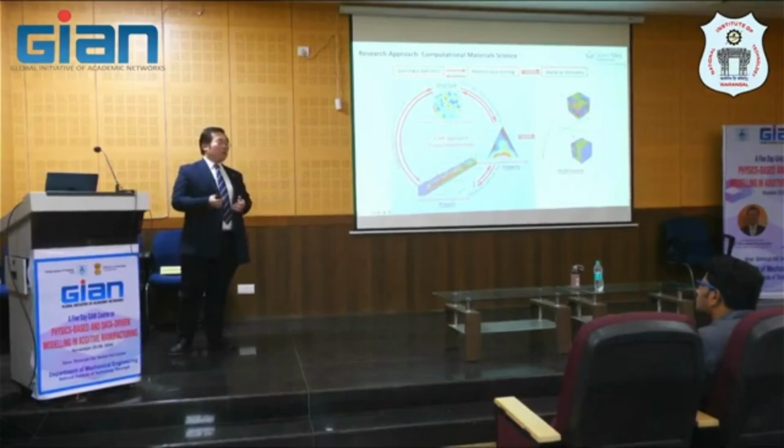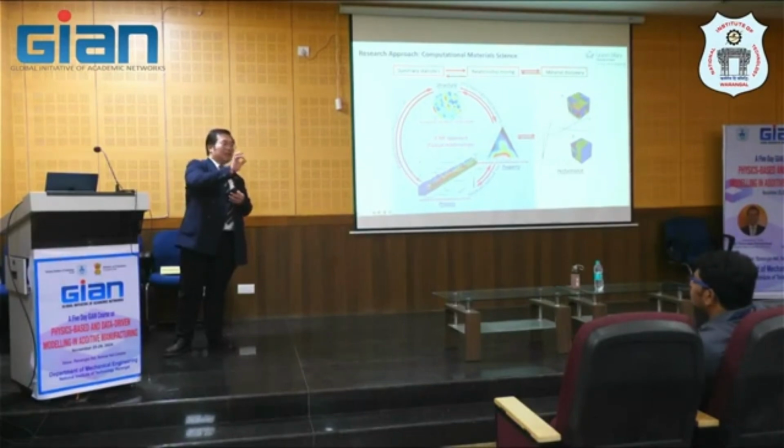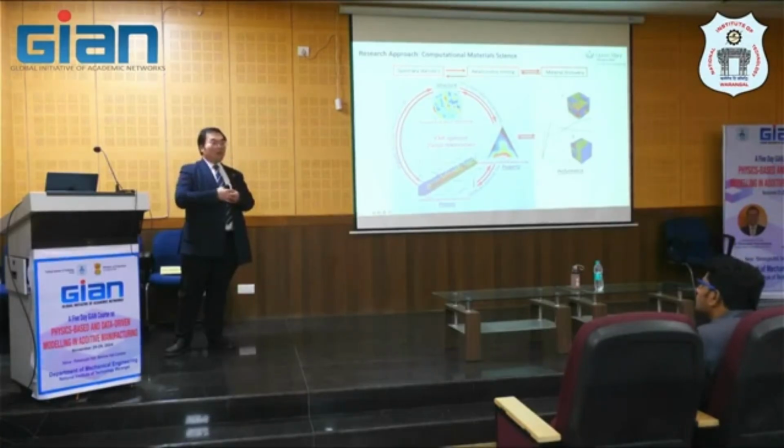And you will see a lot of papers in additive manufacturing talking about the effect of that. Another factor of low quality powder is that you may introduce some gas trap porosity inside the powder, and this actually contributes to the final product defect. We already published this work as well in Nature Communications on the detailed pattern of the fluid flow that makes pore coarsening up to probably 0.5 millimeter, quite a large pore, which is detrimental for aerospace repair, for example.